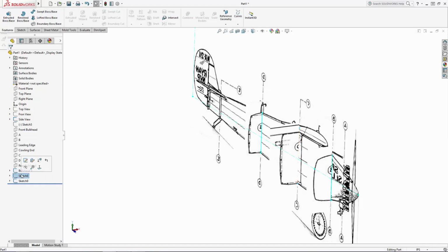With our initial layout in place, this concludes part 1 of the series. As you can see, using this 3-view technique to model takes a bit of time in the initial setup, but bear with us. In part 2 of our series, we'll start picking up momentum by adding in our profile sketches, and we'll begin modeling the fuselage using the Lofted Boss tool.